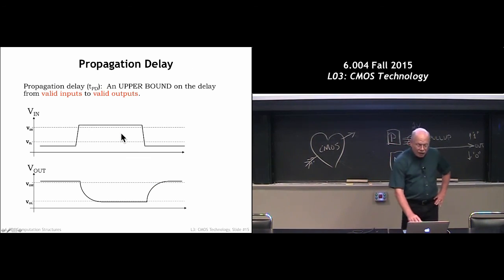Alrighty, so how do we do the measurements? Here I'm being very careful. I'm looking at when the input node becomes valid. So the input node becomes valid when it crosses the VIH threshold. That's when it's suddenly now a legal 1.